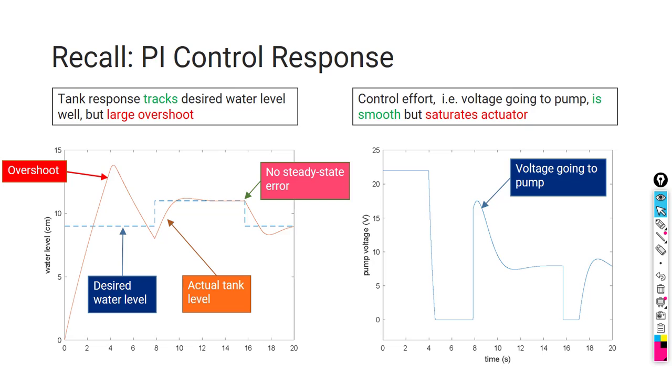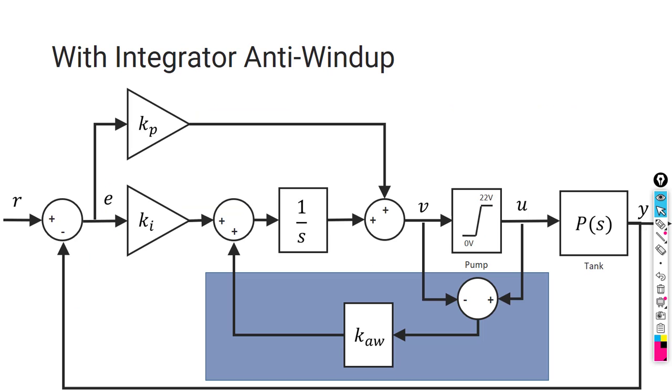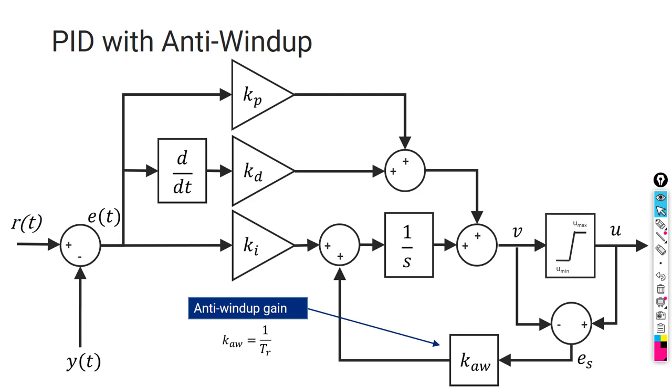It's called KAW. They call it AW because of anti-windup. That's a symbol. You can name it any constant you wish. Later on we'll see how to design for it. But for now, you can do the same for a PID controller too. Here we don't have space to continue the block diagram, that's why I'm feeding it like this.